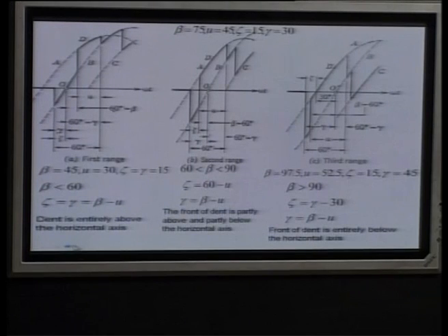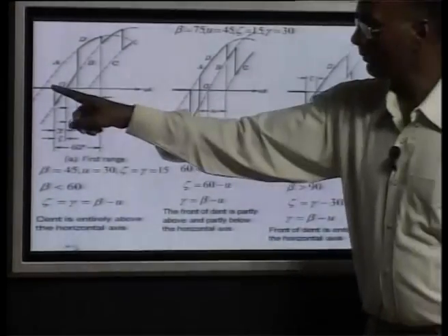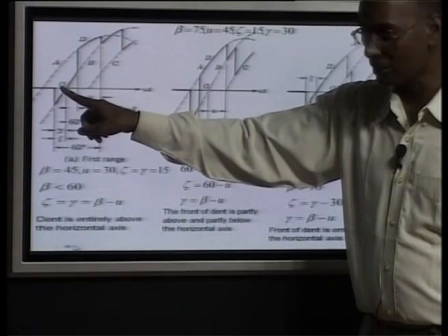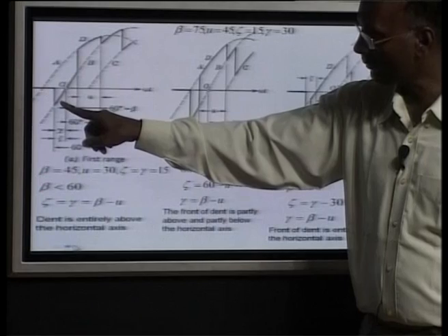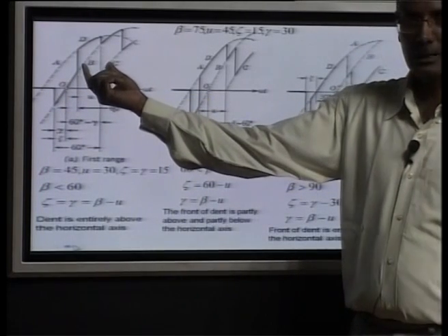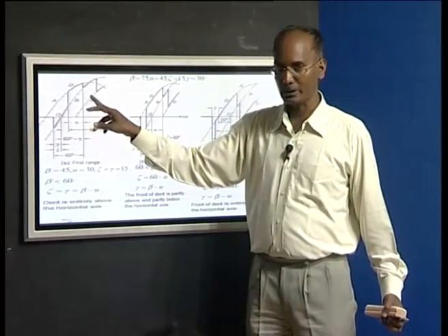Here you see the various configurations, various possibilities. The previous figure was similar to this. You can see valve 3 was conducting, the commutation of valve 3 was off here, and then it followed this voltage and goes here. In this period there is a 3-valve conduction mode.